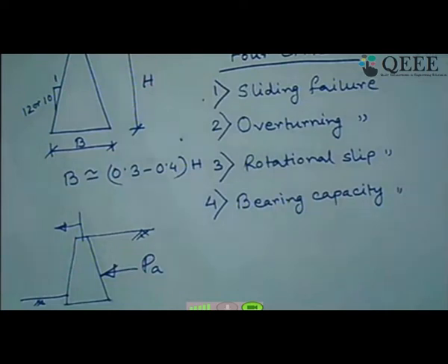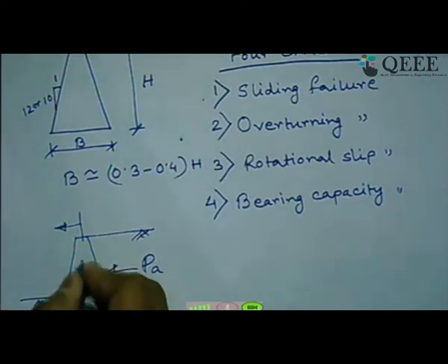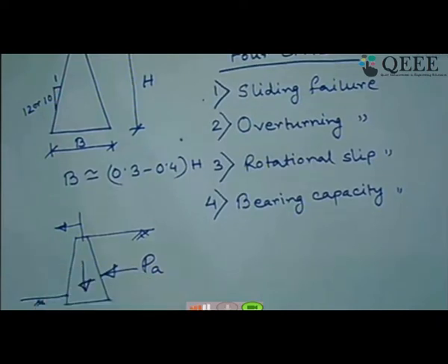So how we will do that? So this is your disturbing force, essentially earth pressure force, which creates the sliding, and because of your weight provided here, you will have a reaction here, and that will give you a sliding force, a resisting force for sliding over here, which is nothing but mu times of N. Mu is the coefficient of friction between the wall and the base soil.